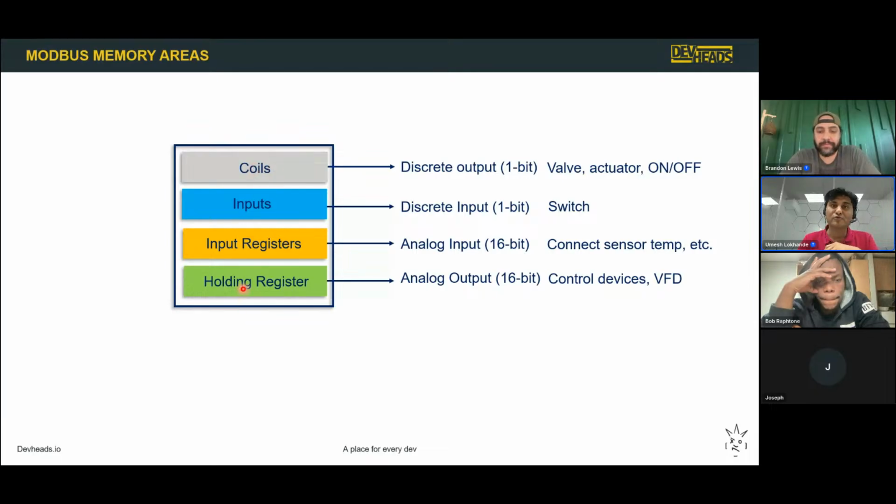And when you want to read the data from the Modbus compatible device, then you store it into the holding register and then you read. There are 2 things in the world of embedded. What you do in embedded, you write and read from the device, right? That's what is called embedded in short. Okay, so just focus on coils and holding register.